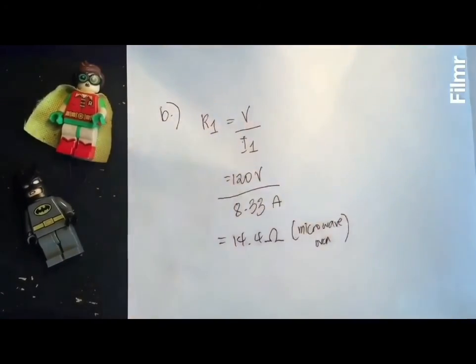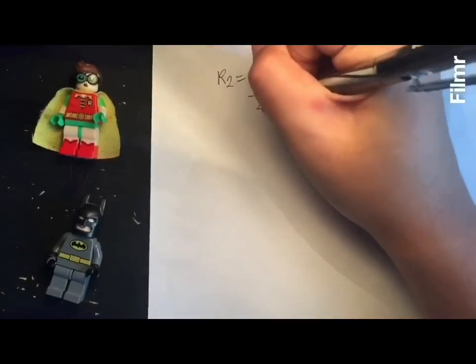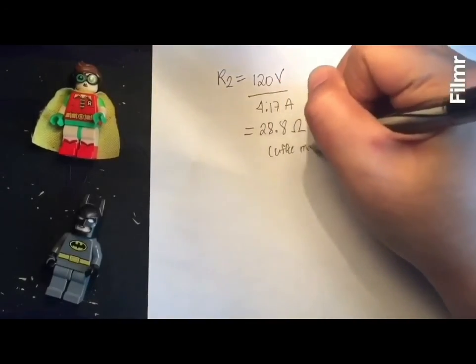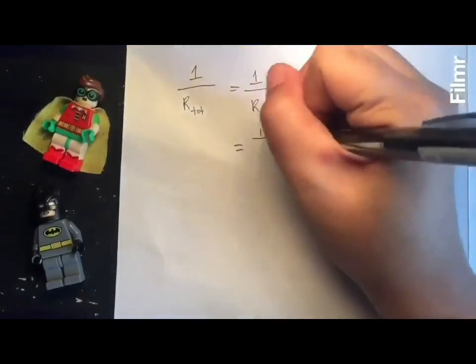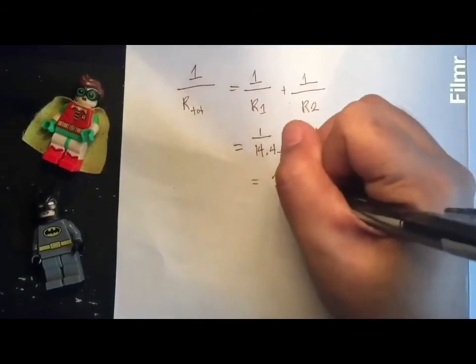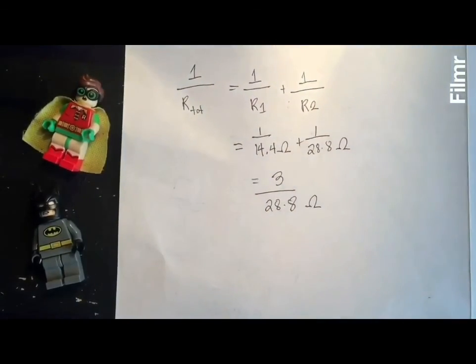Solution letter B. We can use Ohm's law or either of the power equations involving R to find the resistances. Picking Ohm's law, I equals V over R, and solving it for R yields the resistance. Note that the full voltage is used since the resistances are connected in parallel. This cannot be done for resistances in series. Now, the total resistance can be found.